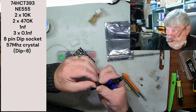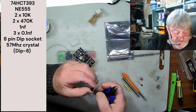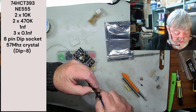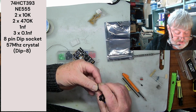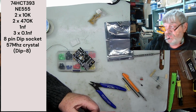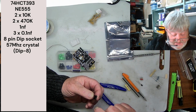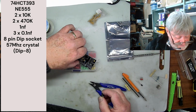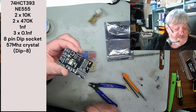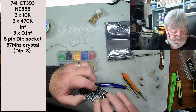Just like that. So it takes them out, because if you don't take them out, you'll have to bend them, and then if you're short on anything, it could cause you problems. But if I just remove them, it's only an 8-pin socket. If you haven't got an 8, get a 16 or an 18 or something, standard size socket, and cut it down so it's 4 either side, and then that can just sit down into here, and we can solder that in and plug our IC in on the top.